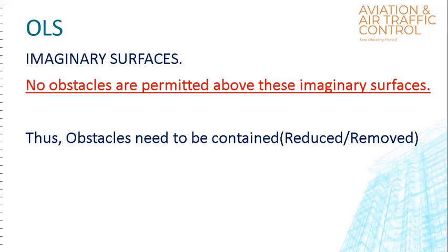Obstacle restrictions: objects, except for approved visual and navigational aids, must not be located within the obstacle restriction area of the airport without the specific approval of the Civil Aviation Authority. Equipment and installations which are required for air navigation purposes are to be of minimum practicable mass and height. These should be frangibly designed, mounted and sited in such a manner as to reduce the hazard to aircraft to a minimum.